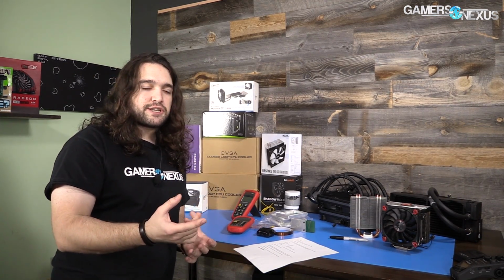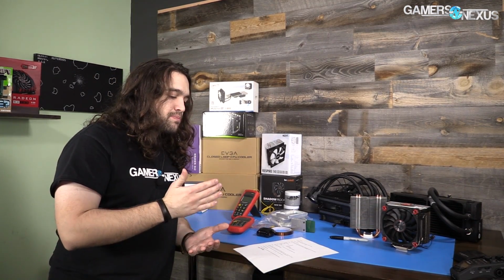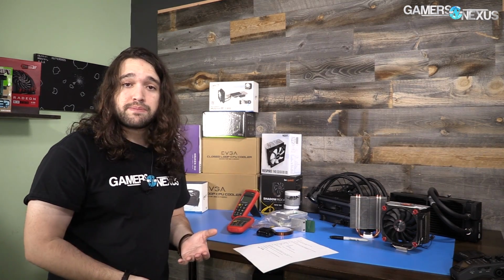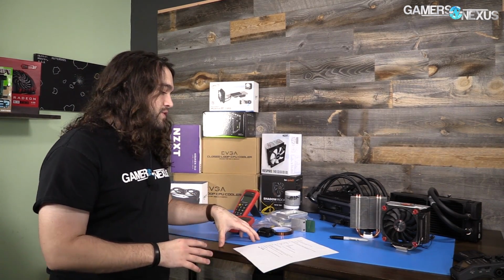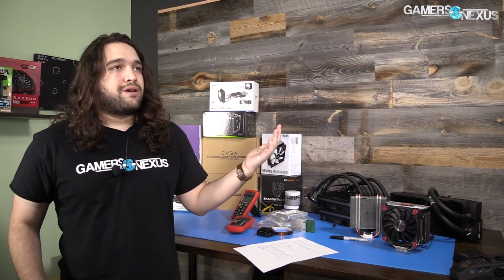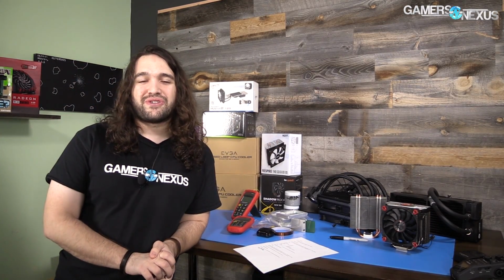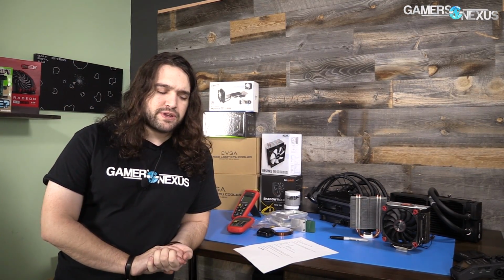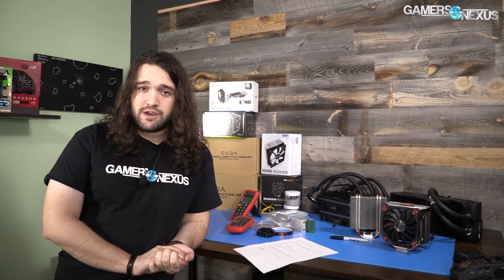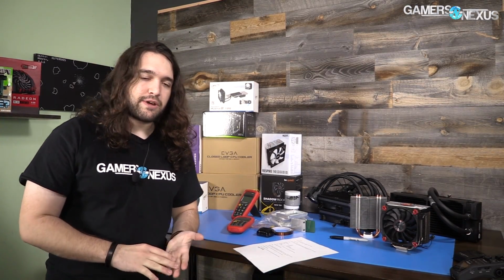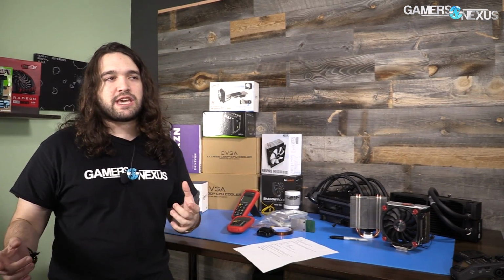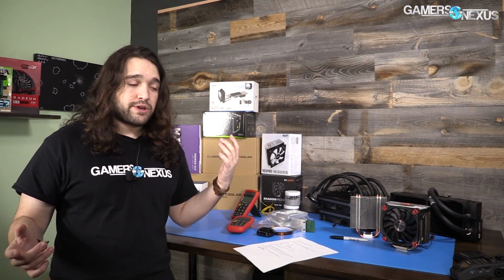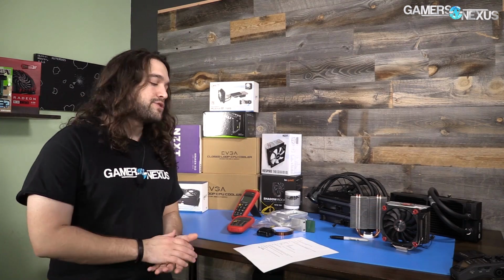So that's an AMD thing, and that's not just AMD, it's the software. With Zen, this might change, but software pulls data from sensors in the chip, and you need to understand what values you can trust. For example, with Kaby Lake, it was kind of difficult with all the core temperatures. The software didn't work quite the way it has in the past, for the immediate versions anyway. As they update, it might change. But for Kaby Lake, you want to use CPU package through hardware monitor because that's the same as XTU, which is obviously trustworthy because it's an Intel utility.